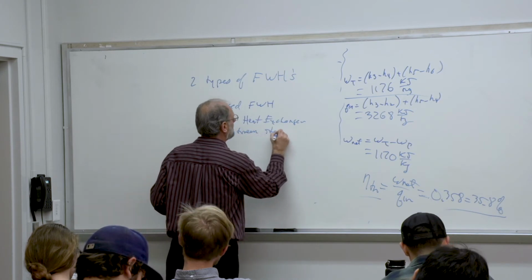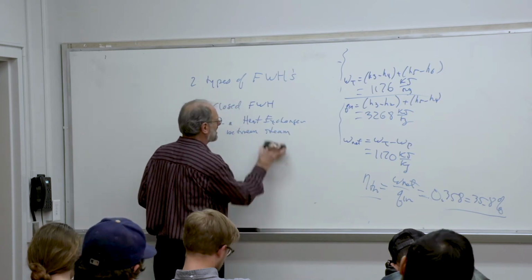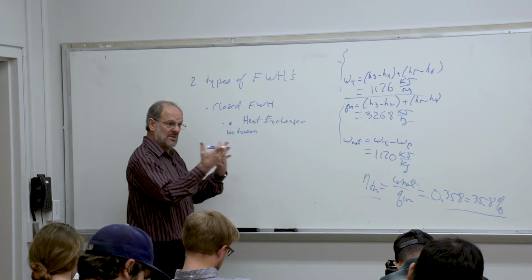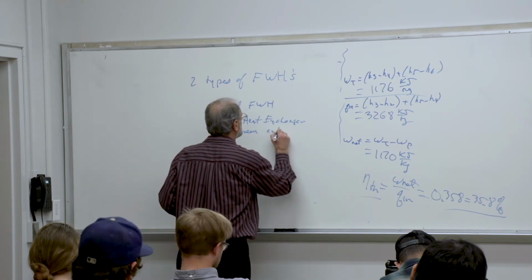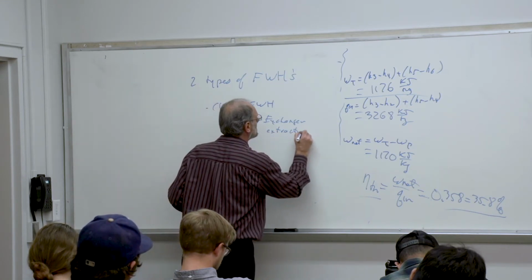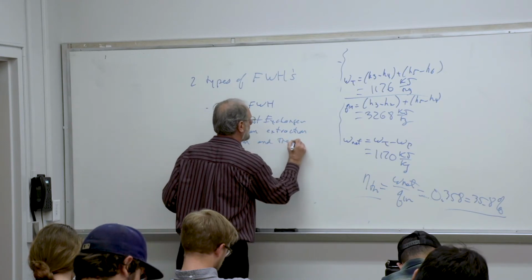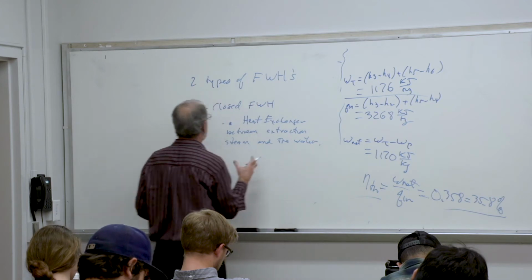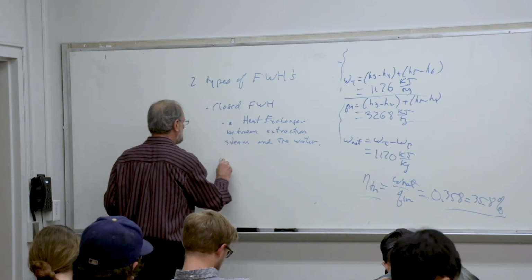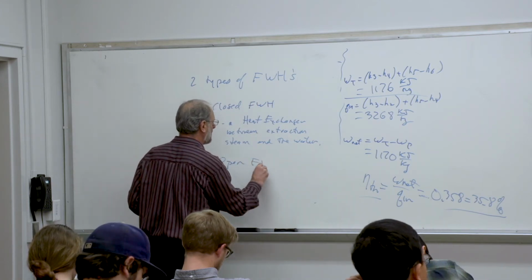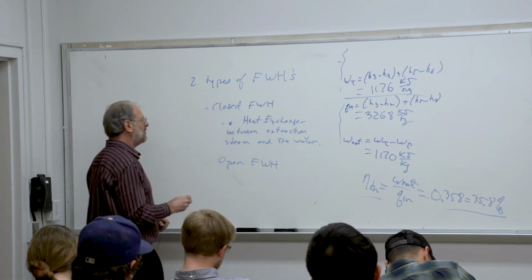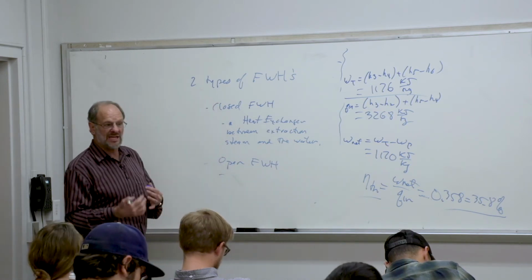between steam. In fact, let me call this extraction steam. That's the steam we're extracting. So between the extraction steam and the water. And the other possibility is what we call an open feedwater heater. In an open feedwater heater, we don't have a heat exchanger.